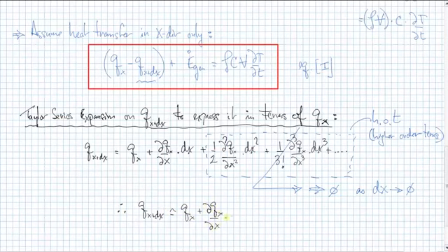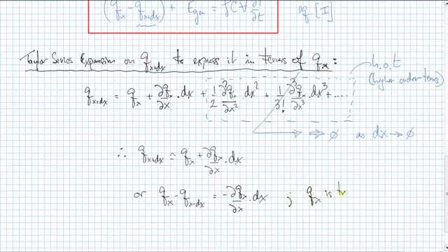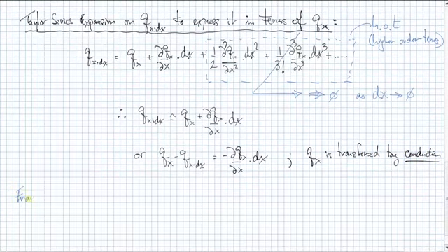Okay, so keep that one in mind. We're going to substitute that back into equation 1, once we've figured out what to do with Q sub x, and we're going to use our first tool, Fourier's law, in order to do that. Our next goal there is to express Q sub x itself in terms of temperature alone.